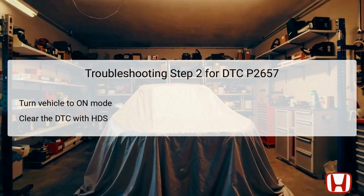If the HDS indicates normal conditions, it suggests that the issue may be intermittent, and that further inspection of wiring connections to the rocker arm oil pressure switch and the powertrain control module, PCM, is necessary. If the failure persists, the next step, which is more in-depth, will have to be executed. The third troubleshooting step involves performing an internal continuity check on the rocker arm oil pressure switch A.